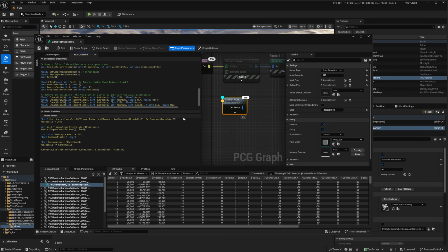So we'll generate 2 random offsets for x and y that go between -500 and 500, and the alpha parameter is a random value generated with frand. Note that the seed will change every time the frand function is called, so I'm not generating twice the same value. I'll remove my random displacement on z and add the random offset for each axis.